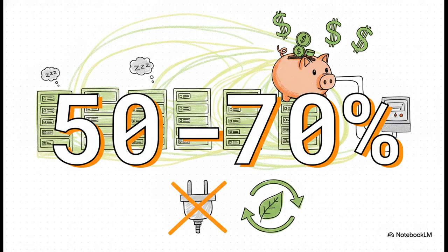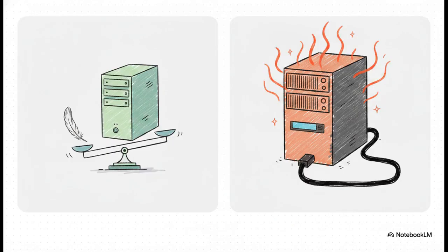No way, right? Let's look at this comparison to see why it's such a massive headache for data centers. In an ideal, perfect world, computing would be beautifully energy proportional, 0 watts at 0 load, scaling up perfectly evenly like a balanced scale. But reality is a lot harsher. A real server burns that 50 to 70% power budget even at a measly 1% load. Why? Because simply keeping the memory refreshed, keeping the networking cards listening for data, and keeping the motherboard powered up requires a massive baseline of electricity. This is exactly why server idleness is so massively, incredibly costly. Engineers have to fight tooth and nail to either turn idle machines completely off or pack them totally full of work so that 50% baseline penalty isn't just wasted.